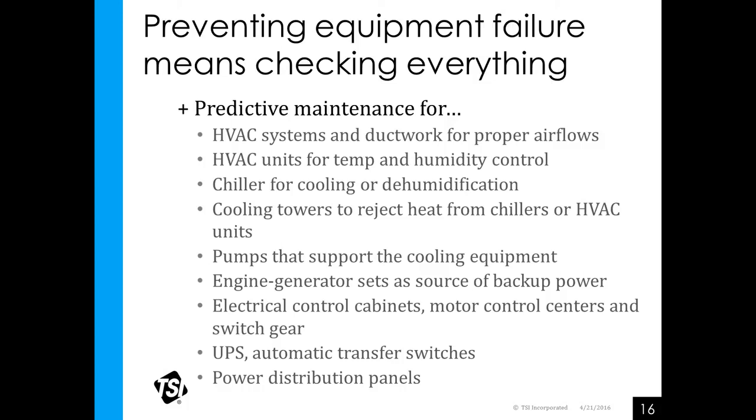And it's not just direct measurement. I mean, there are now non-intrusive technologies you can use in predictive maintenance, like vibration analysis, using a spectrum analyzer to record different waveform signatures, infrared thermography to detect potential problems before a failure occurs, and even ultrasonic flow meters for hydronic flow measurement, for VAV boxes if they're there, to make sure that there's enough water, hot or cold, to do the job. A good indication here would be taking an IR gun to take a look and see, is there a problem about to happen?